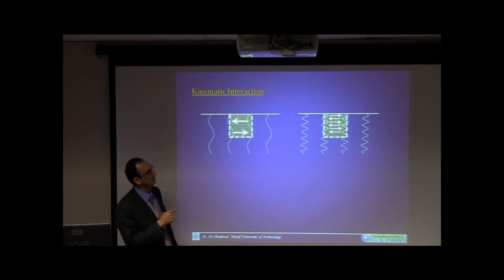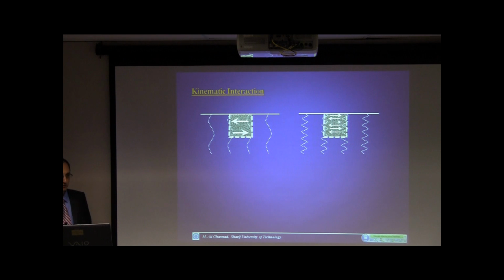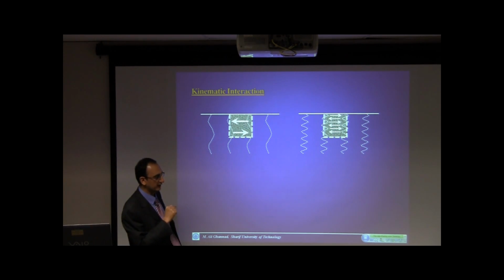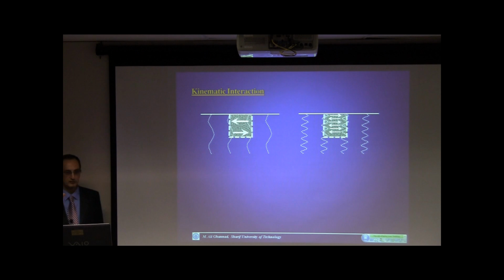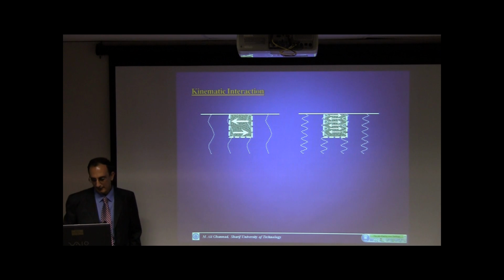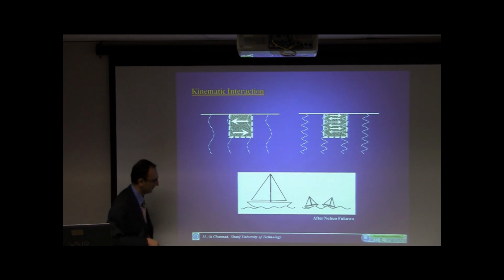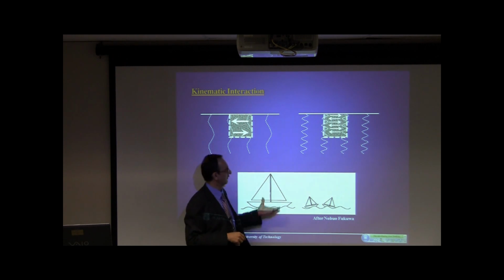So it means that the relative dimension of the foundation to the wavelengths is a key parameter. The high frequencies can be filtered by the relatively rigid foundation, considering that the seismic waves are a combination of different frequencies. And finally, we usually use that for the cancellation of the higher modes.